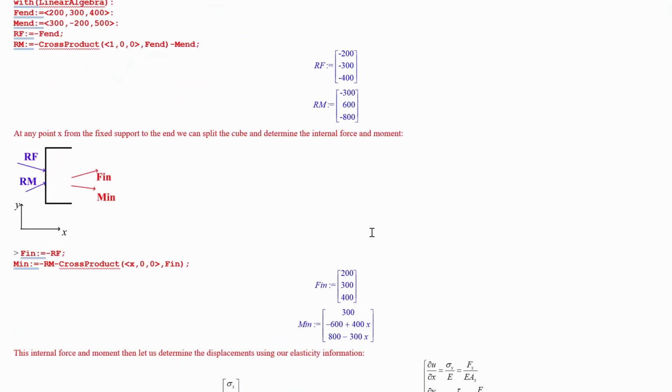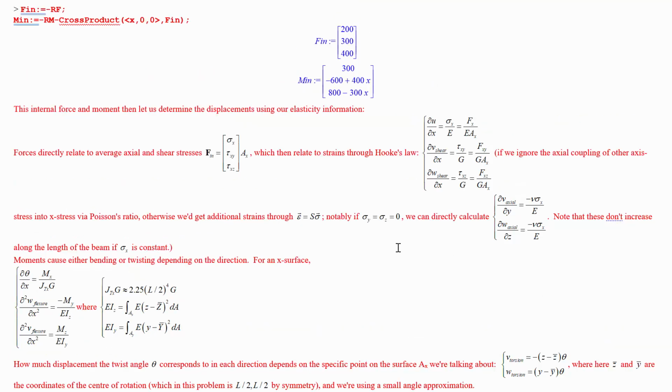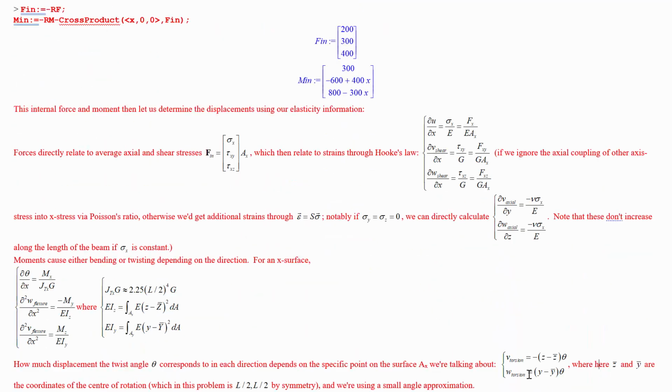So here we are saying that the displacement in the y direction, which is to the right, is based on how much we've displaced in z times theta, and the displacement in the z direction is based on how far we are up in y times theta. Let's just check that. How far up we are in y times theta in the x direction is going to make us bend towards z, and that's why we have a positive number there.